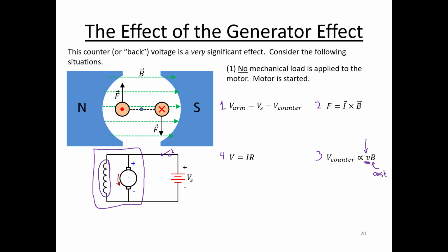Well, if we look over here in our DC motor, again, we've got a DC motor type here, which is common, where the field windings are in parallel with the armature, electrically in parallel. And so whatever we're doing on the armature doesn't really affect the voltage difference that's applied to the field windings, because the field windings are in parallel with the armature, and they're also in parallel with the source. Right, there's our DC source.